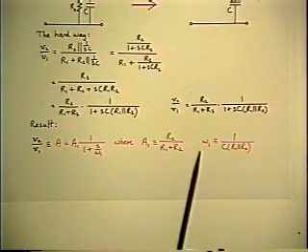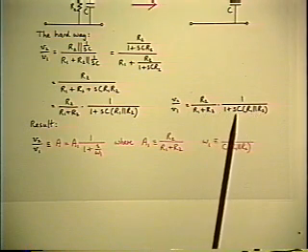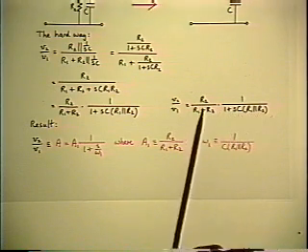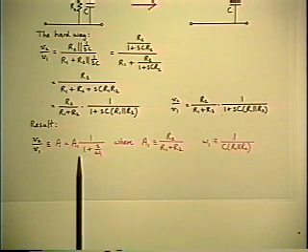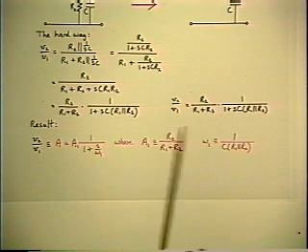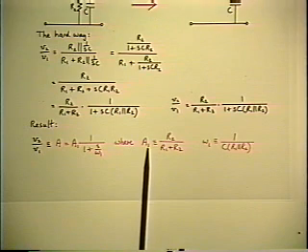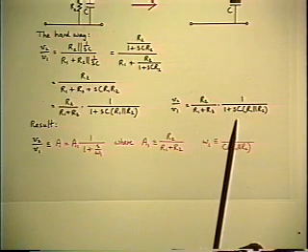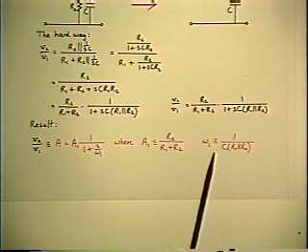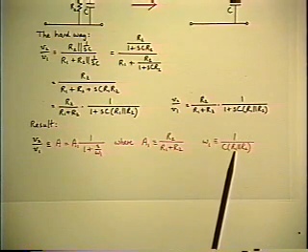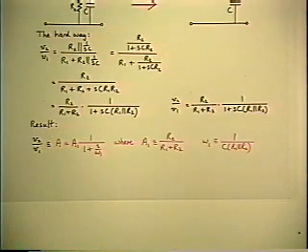Salient features means the coefficient in front and the coefficients of the S terms. Because the coefficient in front has the interpretation of a gain, in this case a loss, but it's a gain factor. So call it some symbol like A1. The coefficient of S has the dimensions of reciprocal frequency, so you define it as the corner frequency. In this case, the capacitor together with the 2 resistors in parallel.